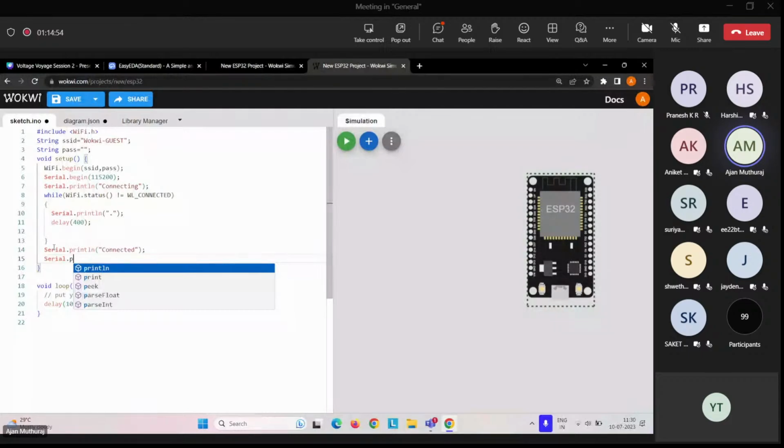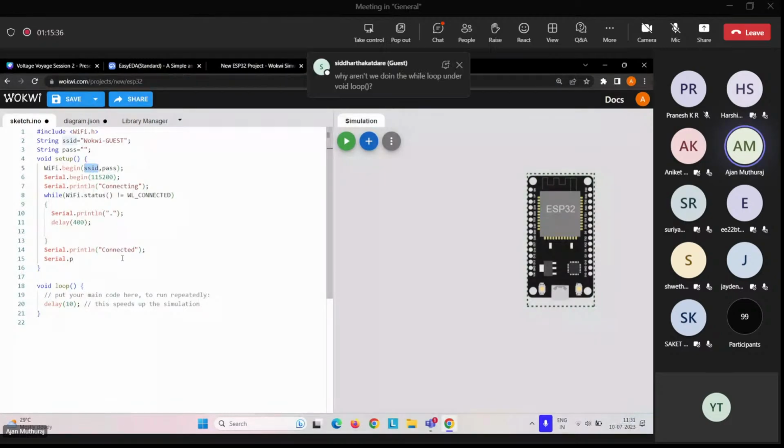So WiFi.begin is an important function to begin connection with the Wi-Fi network. We have considered a virtual router, so it will start establishing connection with the virtual router. Its format is that we first put in the SSID, then the password. If you are using this in real life with a real ESP32, you'll need to use your network's name and password. Fine, right?